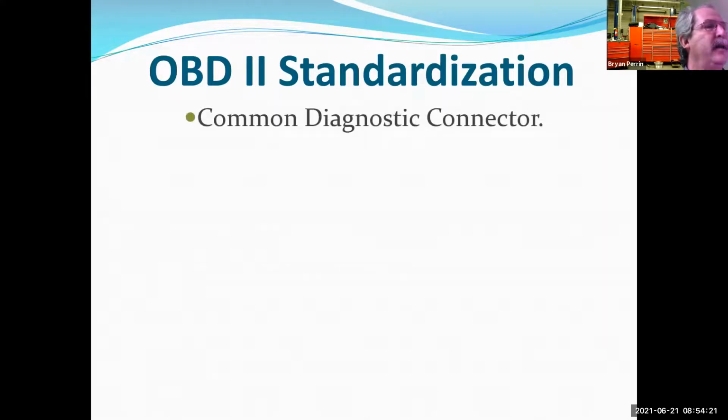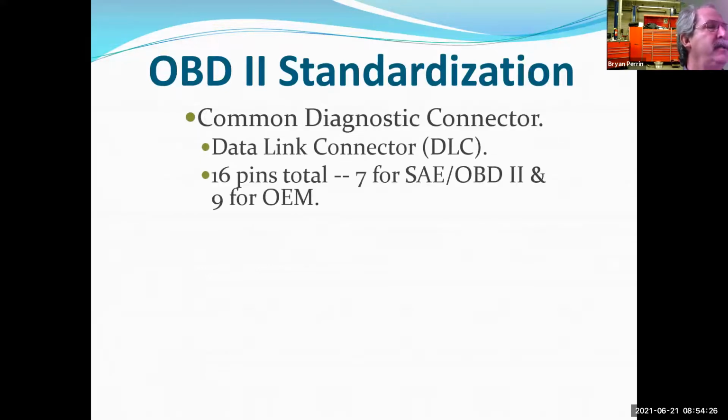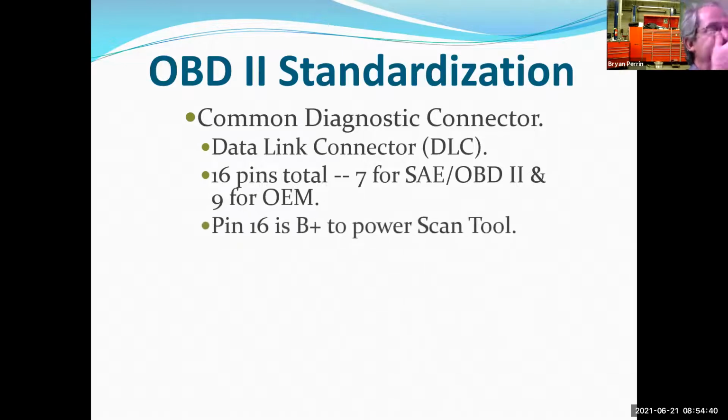So the common diagnostic connector, which is our DLC, has 16 pins total. 7 are regulated by SAE. 9 of them are whatever the manufacturer wants to use them for. Pin 16 is always battery power for the scan tool. That is something I expect you to know.